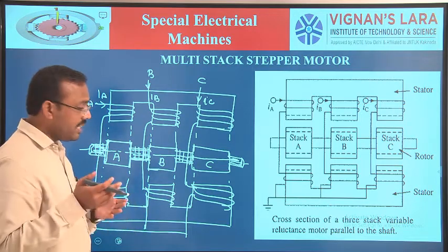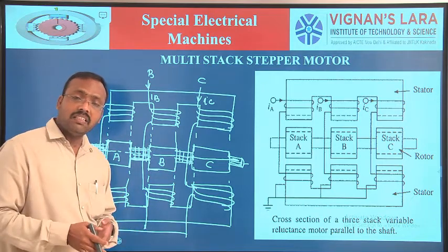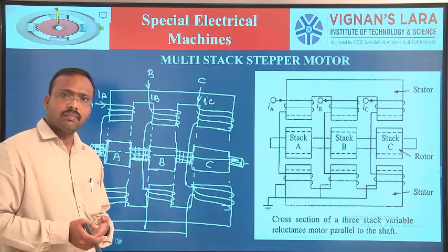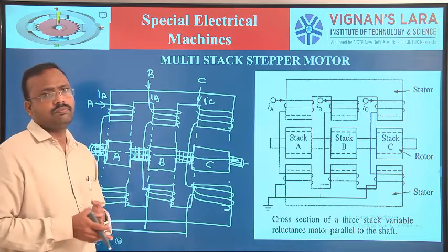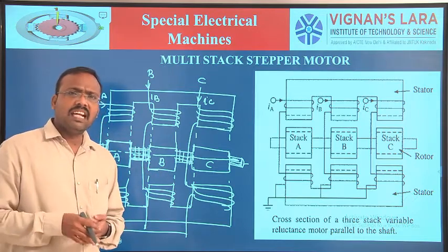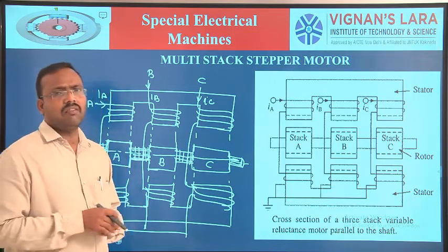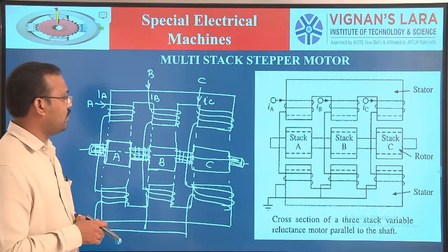Multi-stack stepper motor in the sense that we have separate stacks, each stack having a separate rotor. So what is the use? Compared to a single stack stepper motor, a multi-stack stepper motor offers higher efficiency. Another one is that the torque volume ratio is high.